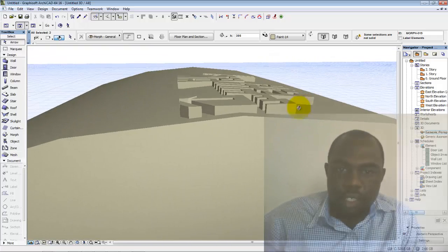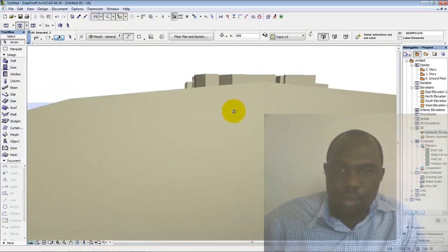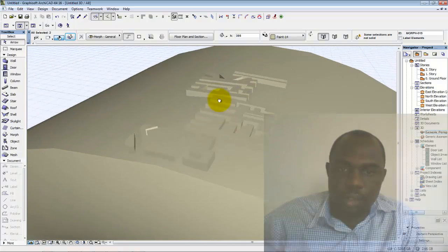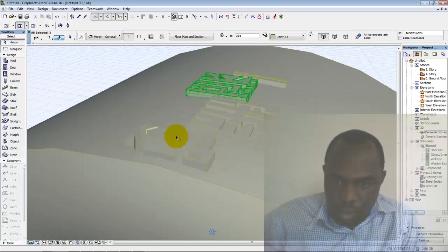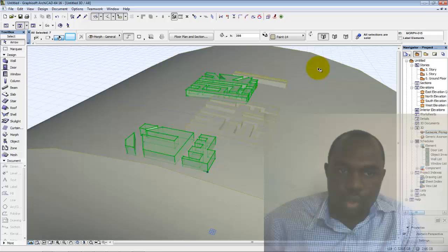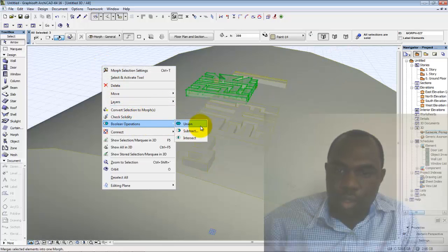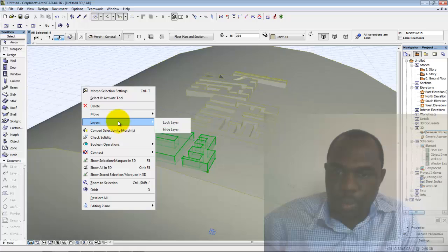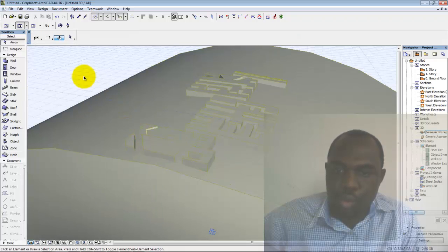So there's an intersection between the tire and the thread. So we have to also convert this one to a complete solid by doing union instead of grouping. Then you select this other one, also do the Boolean operation, union.